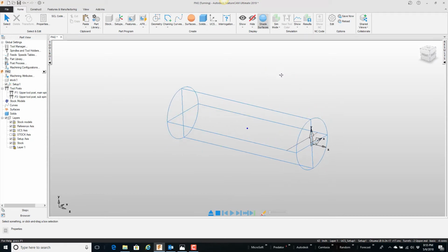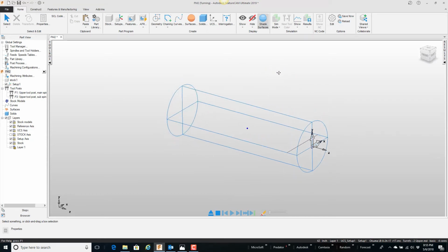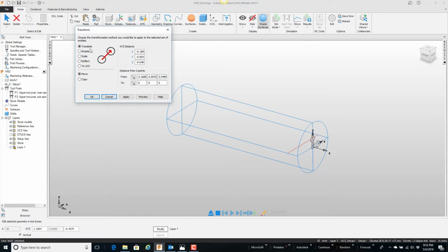Anyway, I have this line drawn. And when I go tell it the top of the curve, if you will, I could tell it, well, it's an inch up. Or I could just take this and translate it up 1 inch, because this is a 2-inch diameter piece of material. I'm going to transfer it up 1 inch in the y-axis. So I'm going to say transform, translate, in the y up 1 inch. Do a little preview here. And I want this to be +1, preview, and say OK.